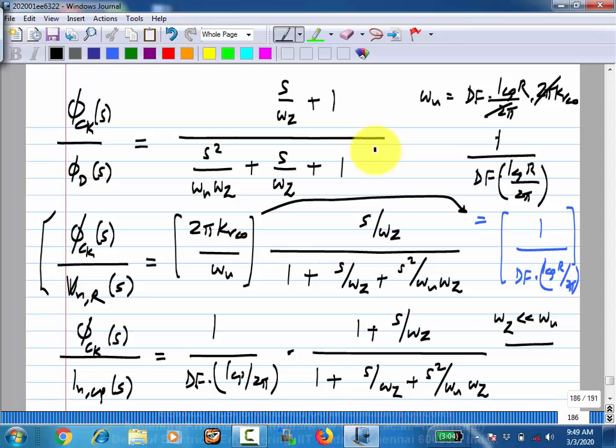Okay. This is fine. So now we have the clock and data recovery circuit without a forwarded clock. So this is what is widely used, especially when you have longer links. Now whether you use forwarded clock or not, it depends on many trade-offs. Typically when you have lots of parallel lanes, and a relatively short distance between the transmitter and receiver, you tend to use a forwarded clock, because already you have so many data lanes, one more lane for the clock is not such a big overhead, and it simplifies the design substantially, right? So the transmitted clock is there, you don't have to recover the frequency and so on. So that's why you use it.